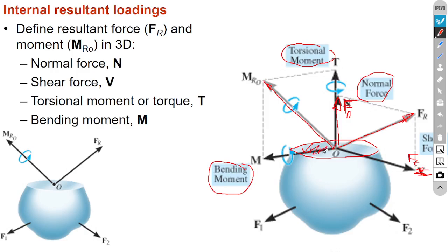Find the area of this surface and then say the normal force F sub n divided by the area of the surface. Whichever cross section you are studying the atomic bonding forces at, use the area of that cross section and write this expression: normal component divided by the area of the surface.